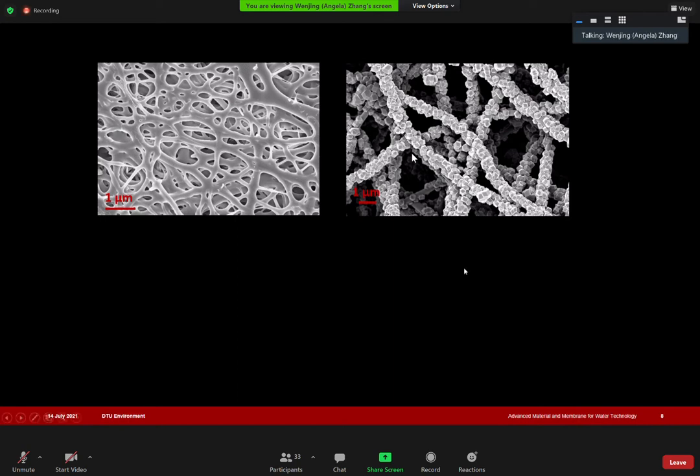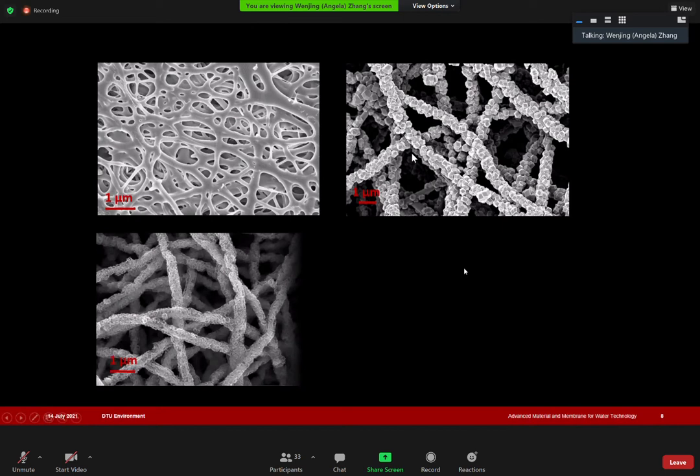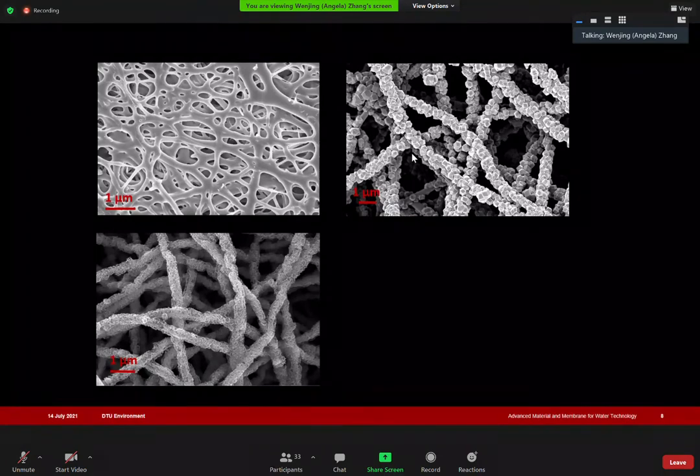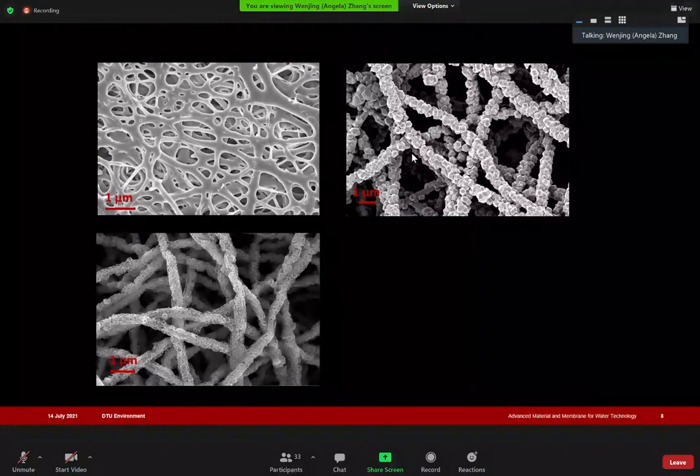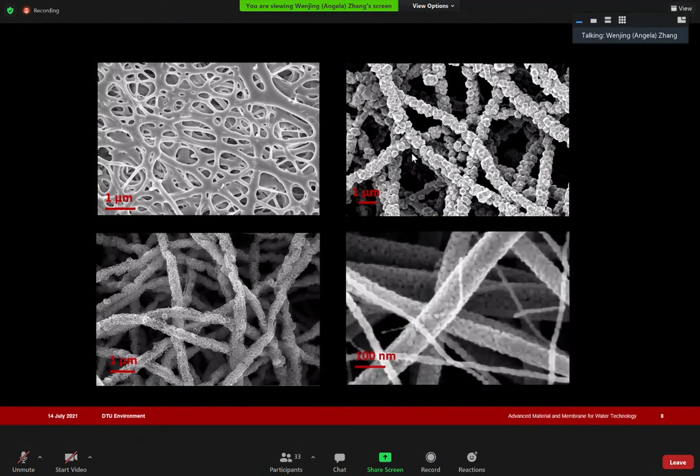If you take those kinds of materials and carbonize them, what you get is a carbon nanofiber. And with metal organic framework, you can also produce nano-sized metal catalysts that decorate the surface of the carbon nanofiber with a tremendous amount of surface area. Instead of carbonization, if you combine sol-gel chemistry with the calcination and sintering process, what you get is ceramic nanofiber membranes.